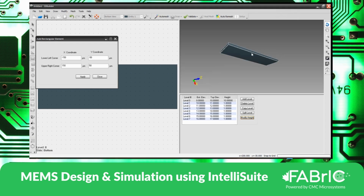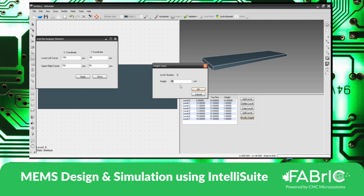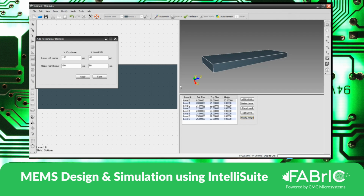So now the thickness is changed. So now level 1 is 10 micrometers. I can select that level, and on the right side you can see the button called modify height, and then I enter 20, so it increases the thickness. Okay.